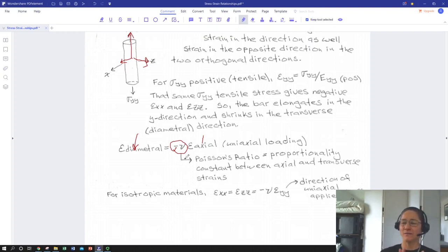Qualitatively, we've covered elastic versus plastic behavior, yield stress as the dividing line between our recoverable proportional elastic behavior with very small strains and our plastic behavior, permanent deformation, usually large strains, higher stresses generally speaking, non-proportional behavior. We've looked at ultimate behavior as being where things break, elastic design where we apply appropriate design stresses and safety factors such that things don't yield, and ultimate design where we do the same thing such that they don't fracture.